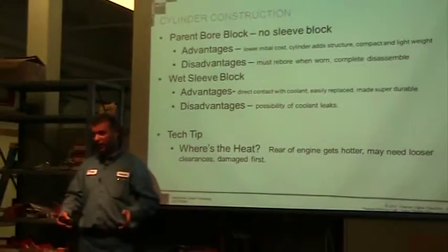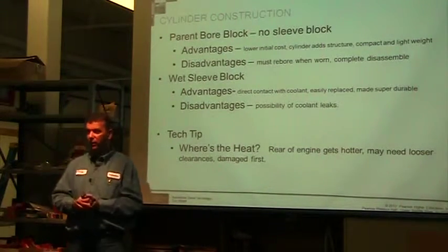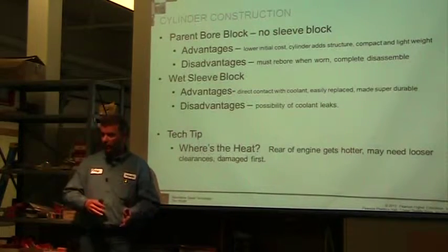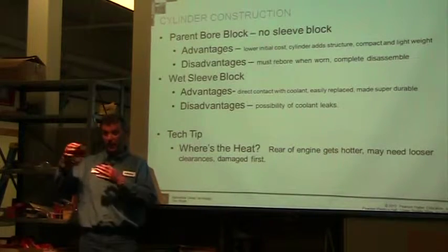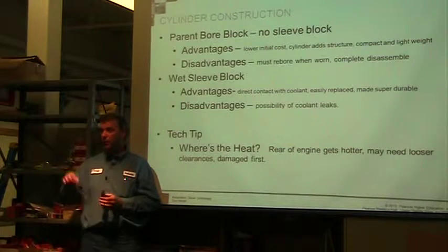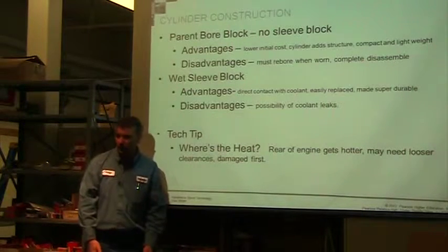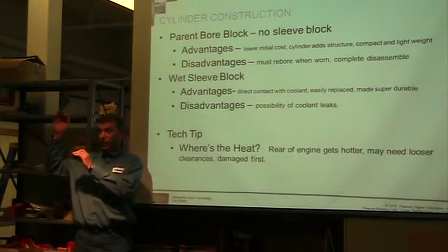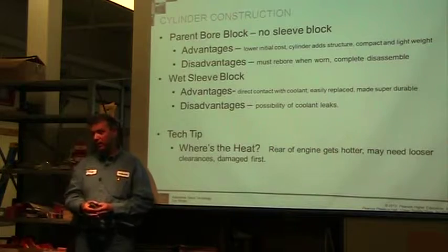Keep your coolant changed. Most coolant is 3 years, you should replace it. We have extended life coolant now that goes up to 10 years. There's test strips that we can test it to see if all the additive package is good. Most people check antifreeze to see if it has a low enough freeze point, and that's it. Well, there's a freeze point and a boiling point. Both of them are critical, and then the additive package is super critical.